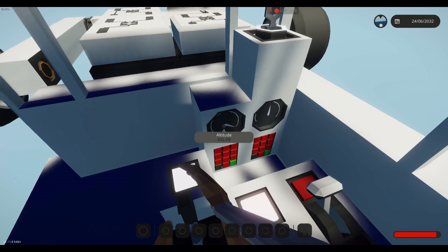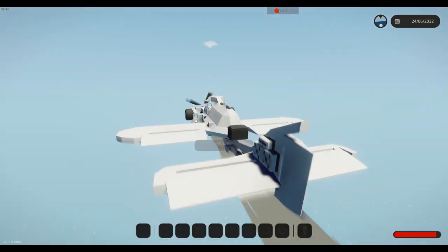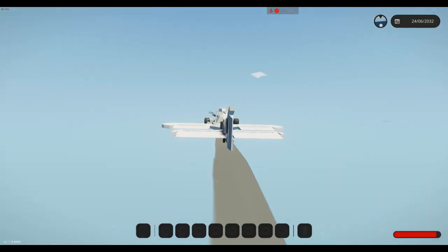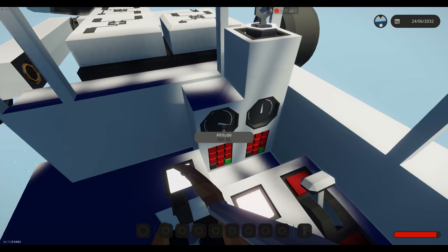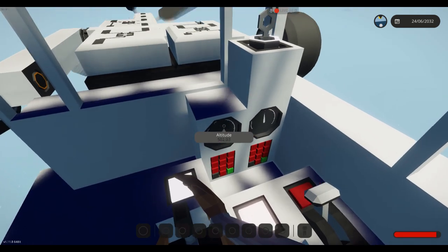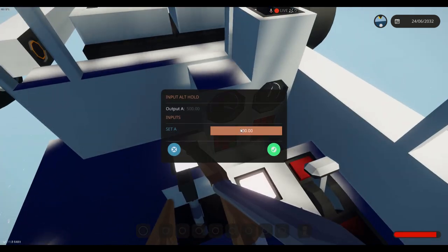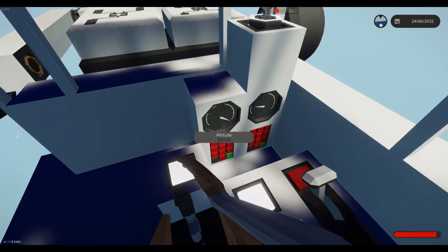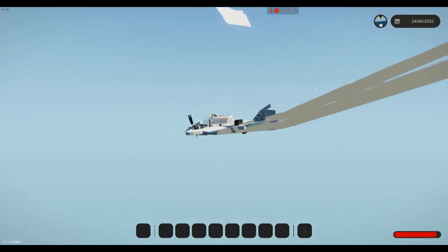501. It was at 501.90, now it's at 502. It is trickling around here. It doesn't seem to be climbing that much higher. There we go, 501.9. I just saw 501.8. It's because of our bank angle. Our bank angle we don't even have set up yet, and so this is perfectly normal. We'll test it one more time. We're going to bring our altitude down to 200 and see what this does.